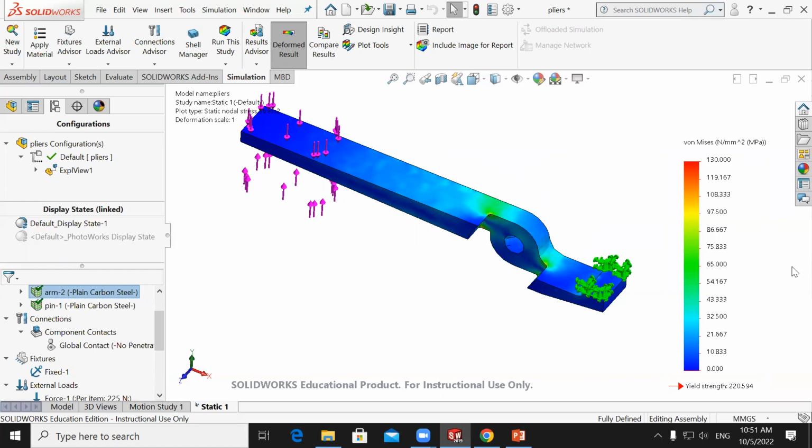But for the result that you get from simulations, the revision of the model is required. You cannot say that is the correct answer yet. You have to make sure of the answer by doing the remeshing and seeing the convergence of the result before the answer.